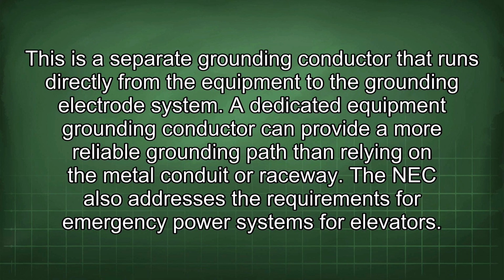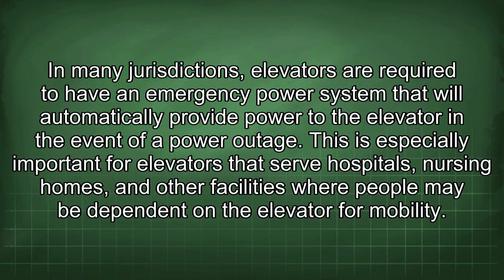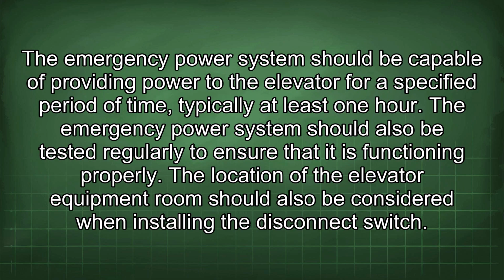The NEC also addresses the requirements for emergency power systems for elevators. In many jurisdictions, elevators are required to have an emergency power system that will automatically provide power to the elevator in the event of a power outage. This is especially important for elevators that serve hospitals, nursing homes, and other facilities where people may be dependent on the elevator for mobility. The emergency power system should be capable of providing power to the elevator for a specified period of time, typically at least 1 hour. The emergency power system should also be tested regularly to ensure that it is functioning properly.